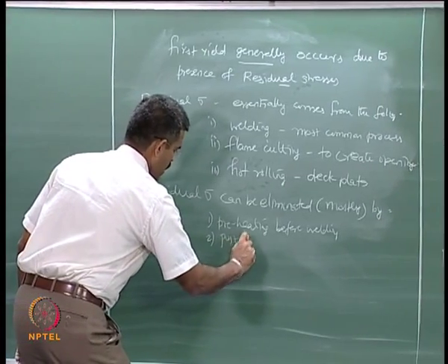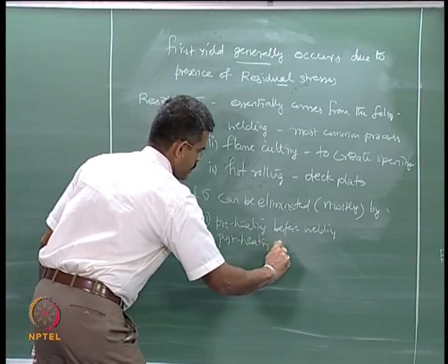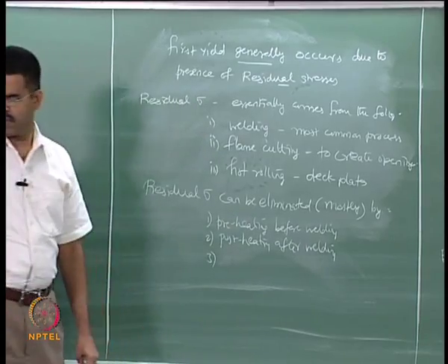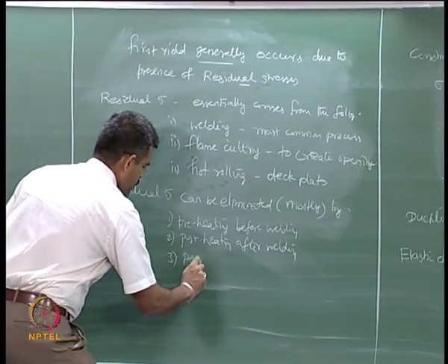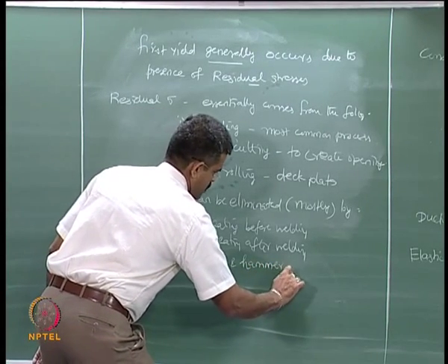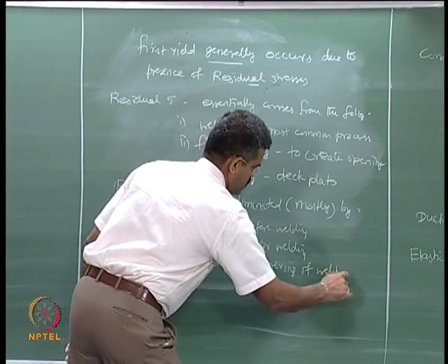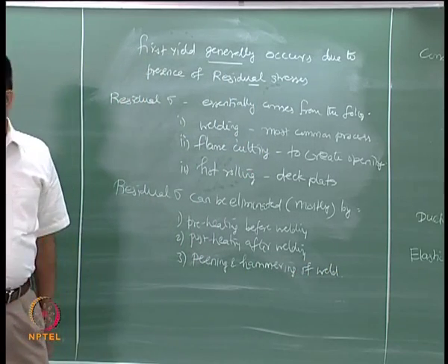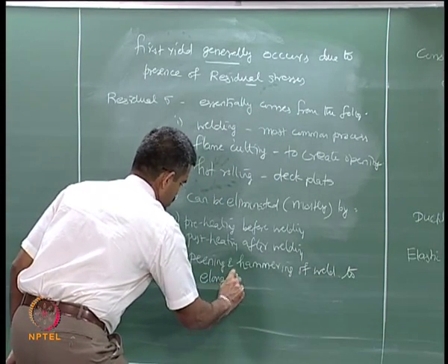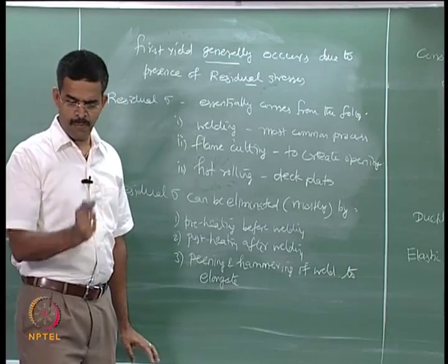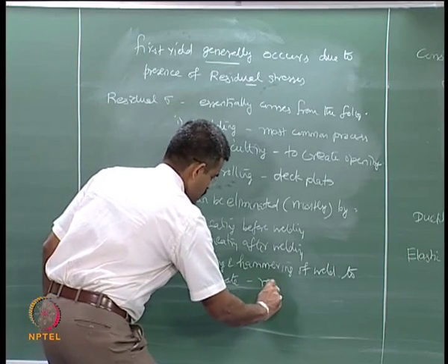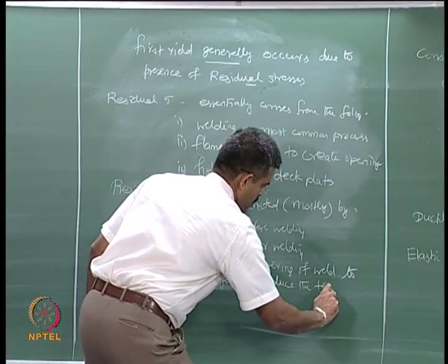Post heating after welding, peening and hammering of welds to elongate. You must have seen in construction sites, after the welding is done, people hit the weld surface to elongate it. This will reduce the tensile stresses.